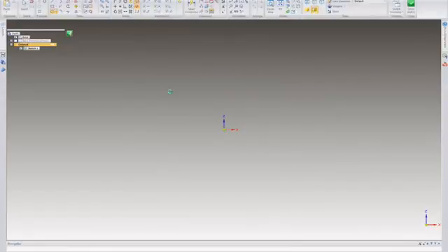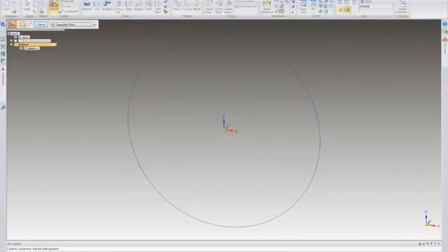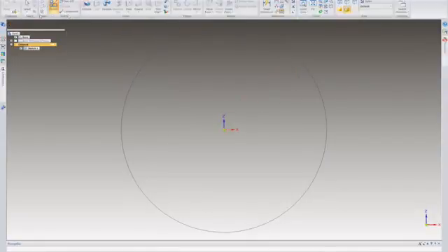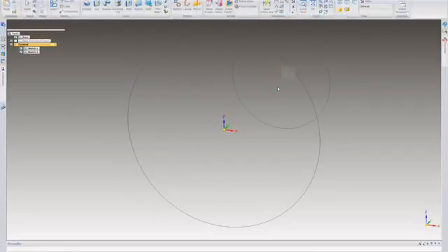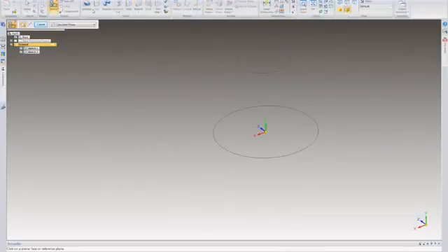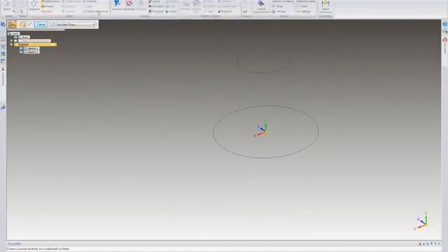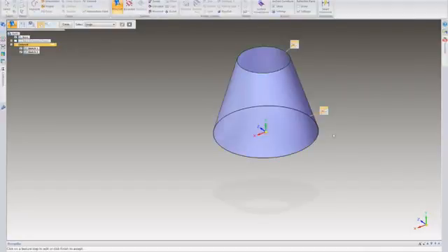All right, so there is no loft command. There is a loft command inside of surfacing, but you would actually have to load it. That's where the actual BlueSurf again takes precedence over the other function. So I'm going to create a BlueSurf between this to get the cone shape that I need. And then I'm going to put some text on the outside of it. I'm just going to BlueSurf from here to that geometry.